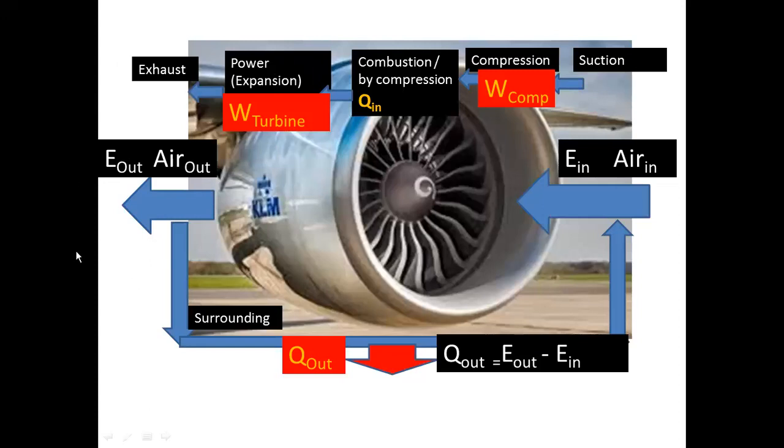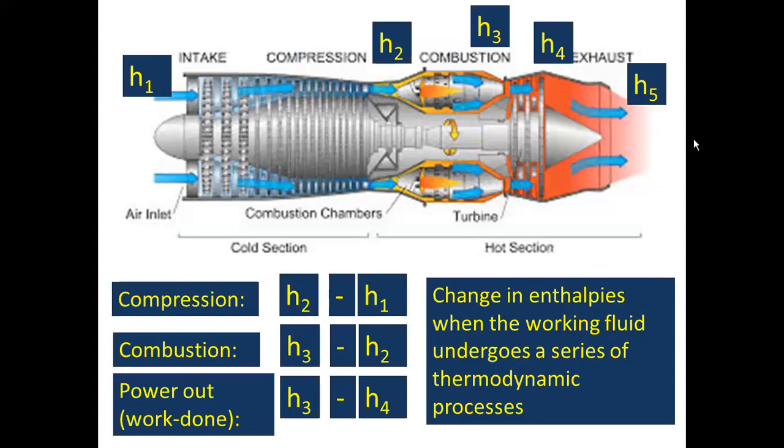That is exhaust. So energy in, energy loss; the compression work is taken from the turbine portion, and there is a net work done. Other than the net work done, for the thrust there is a huge velocity component, kinetic energy for the propulsion. Later we will look into the nozzle effect, not today.